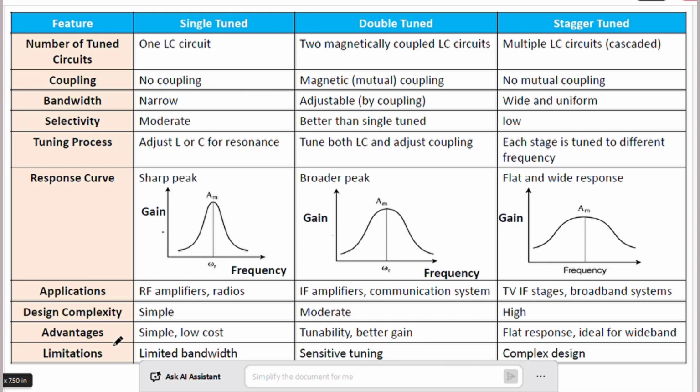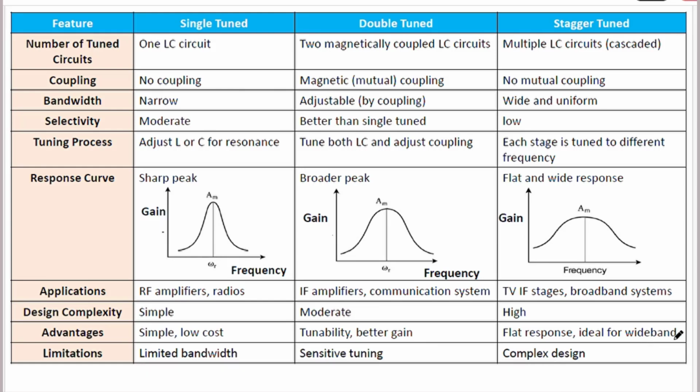Coming to the advantages: single tuned, simple and low cost; double tuned, tunability and better gain; and staggered tuned, flatter response and ideal for wideband applications.